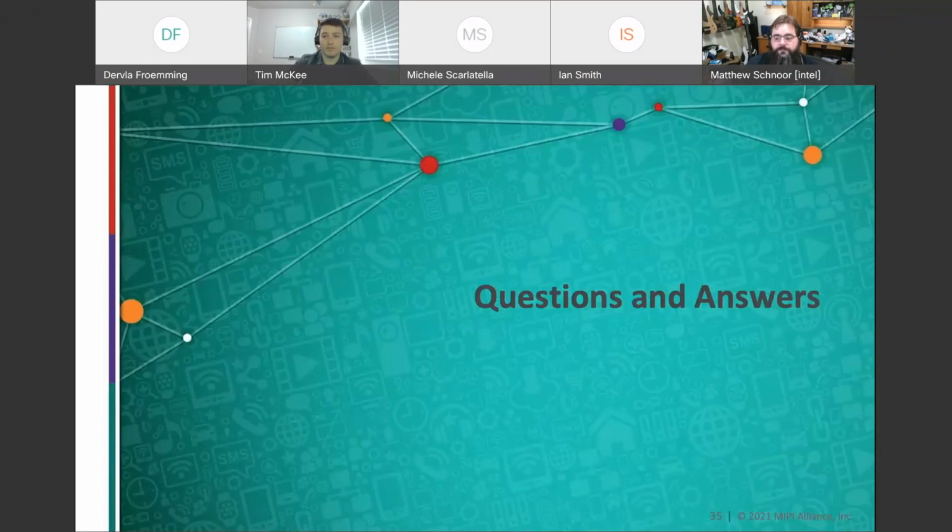Yep, thanks, Michele. So a question regarding hot join, how to handle corner cases. For example, how does the slave know that the bus it is plugged into is actually I2C and it needs to be silent? Similarly, are there many other corner cases? I3C 1.1.1 and I3C Basic 1.1.1 also help to clarify some of this, and you're going to see some of these answers in the FAQ.